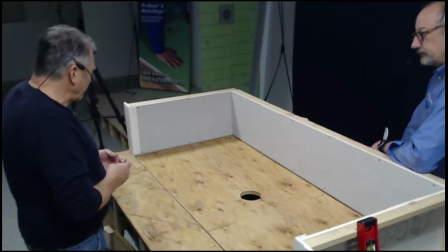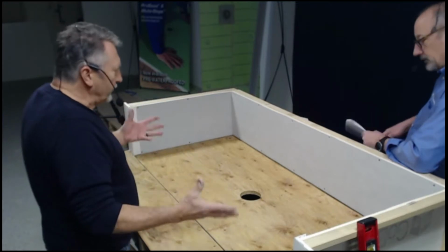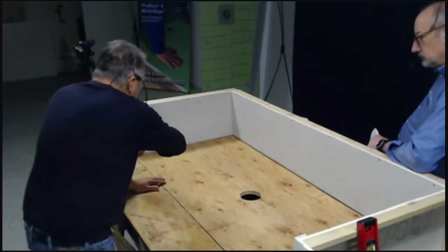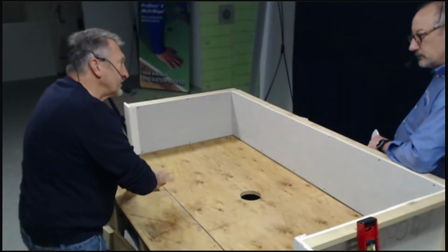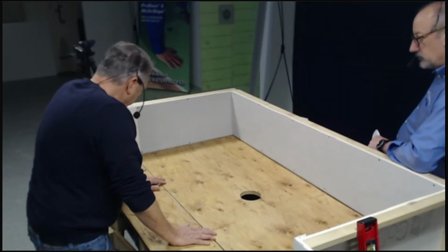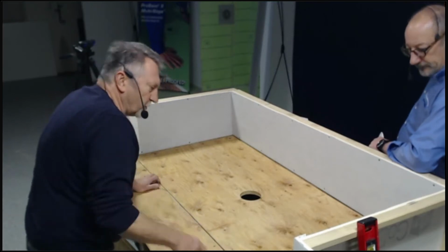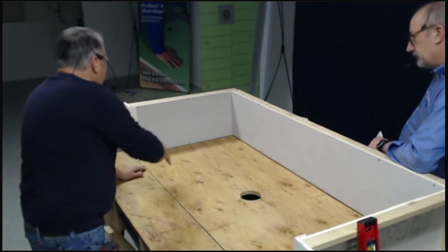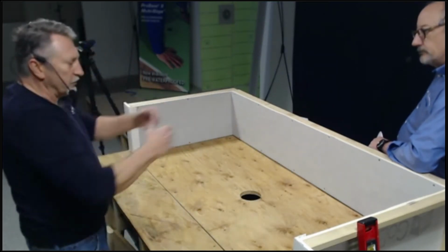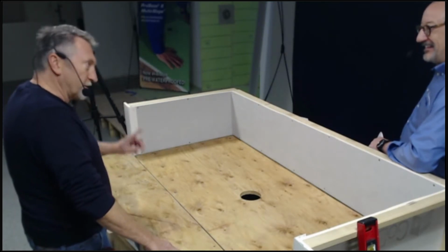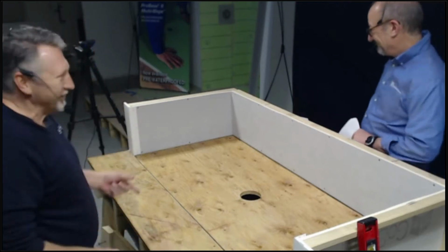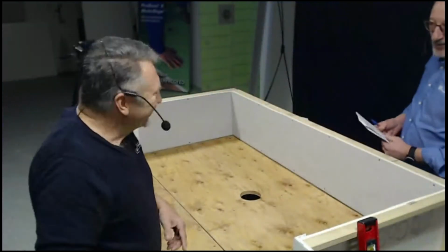Okay, yep. So with that, I can just go around my perimeter, cut out my subfloor, the size of my shower space. Okay? Sawzall or whatever. Sawzall, yeah, to get in there. Skill saw, go around the edge. Yep. With the Sawzall, just make sure that I cut it out at least flush to my backer board. And try not to cut the joists, or get into wires or plumbing. Okay, yeah. Hire a professional, right?